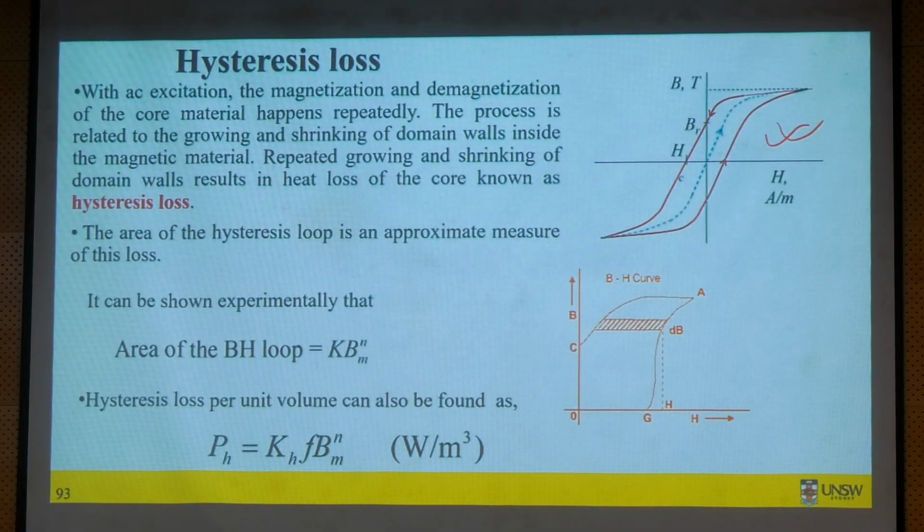Okay? So usually what happens is hysteresis loss and eddy current loss combined together become your excess loss. Okay? When you measure efficiency of motors, you can account for your copper loss, I squared R. You may be able to then find other losses, which combine the eddy current, hysteresis loss, and mechanical loss. Especially in PM motor, we cannot separate mechanical loss from the iron loss. So mechanical loss and iron loss are clubbed together, which you can measure running the motor under no load condition.